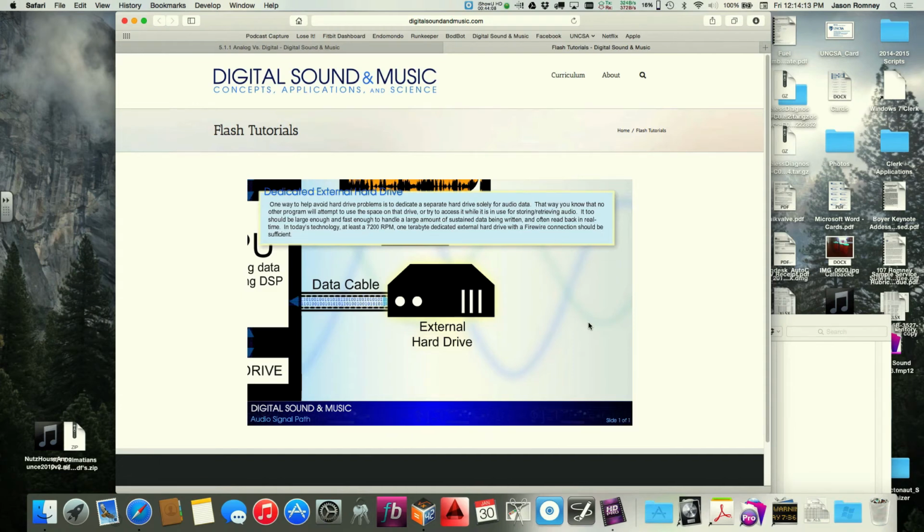And so for audio, when we were buying these FireWire hard drives, we found out pretty quickly that the Oxford chipset performed better and didn't drop out as much. And it was really DigiDesign who zeroed in on this with Pro Tools. They started supporting FireWire drives, and they started seeing varying levels of performance, and they were the ones who noticed with Pro Tools that, we don't have these problems with the Oxford chipset, but we do with others.